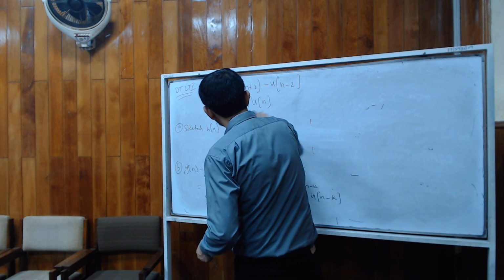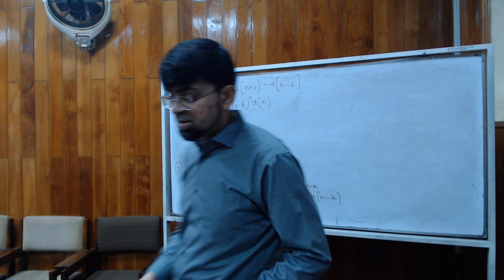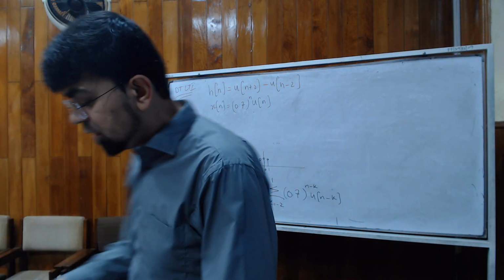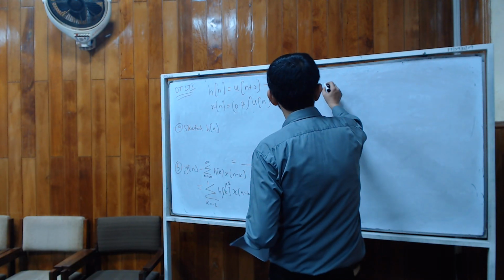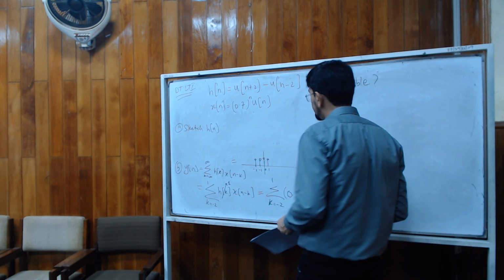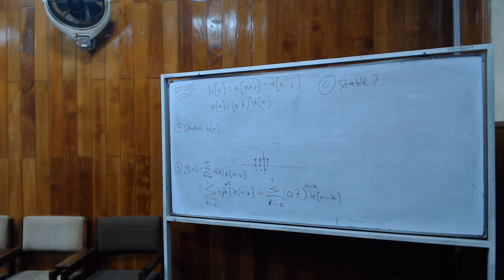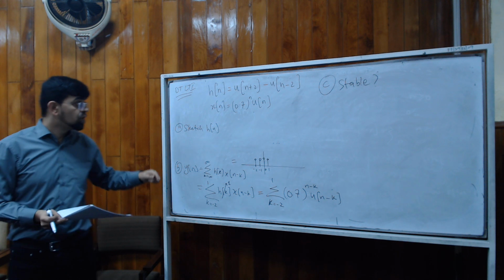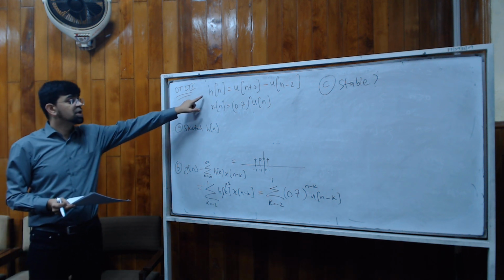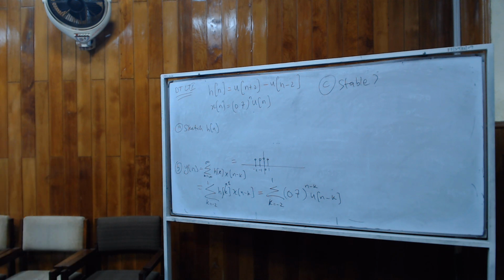Right, so what if now we are asked something additional here? Let's say we are also asked to say if this LTI system is stable or not? Now we could go back to the very general definition of BIBO stability, but as I've already mentioned, for LTI systems, if you know the impulse response, a better thing to do often is to just check stability from the impulse response.